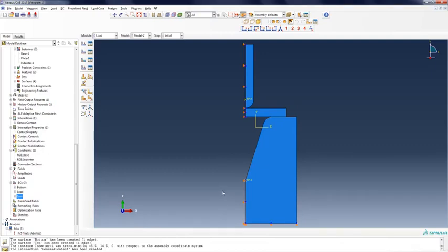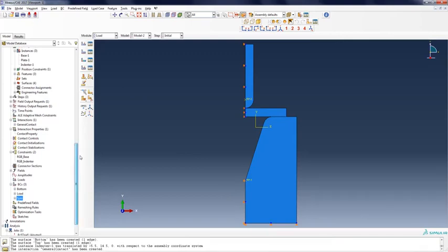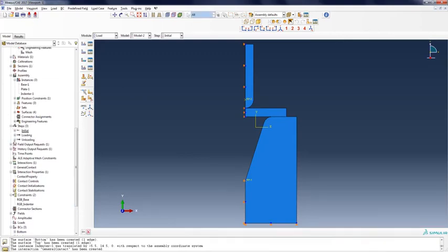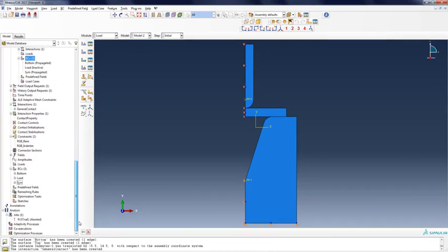So contact defined, mesh defined, boundary conditions modified, we need to go to the last step, unloading, and we need to check that, okay, node is still inactive. So that's for the elastic spring back part. Okay, so we can try again. Create a new job.